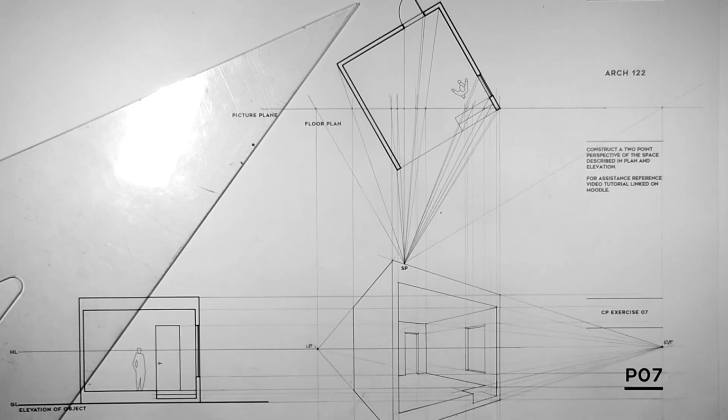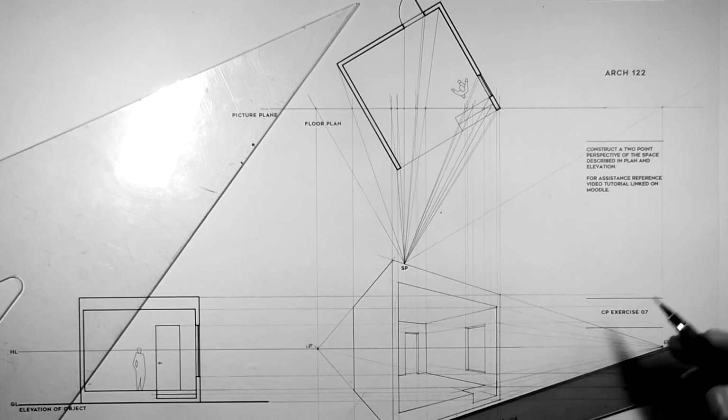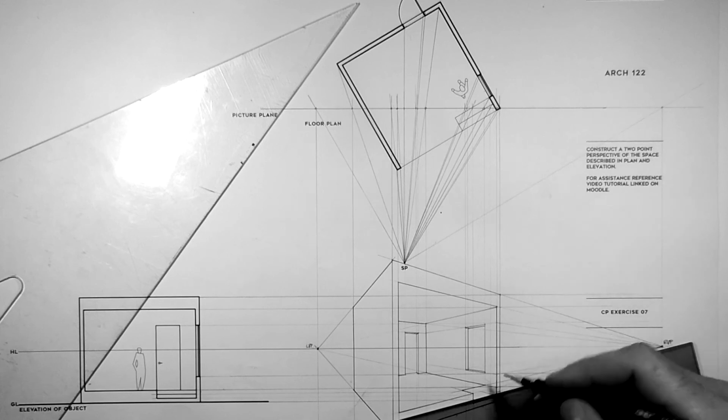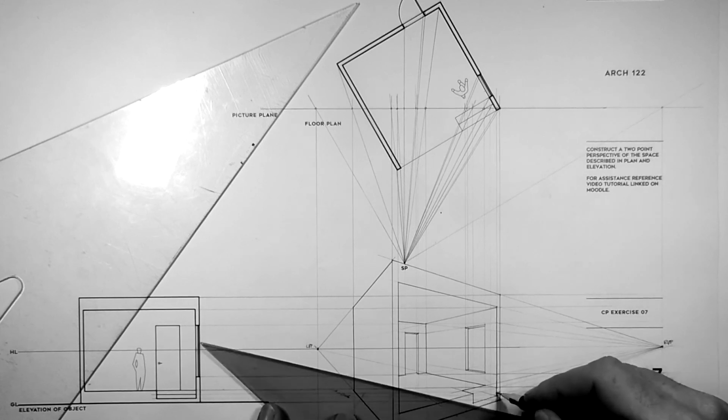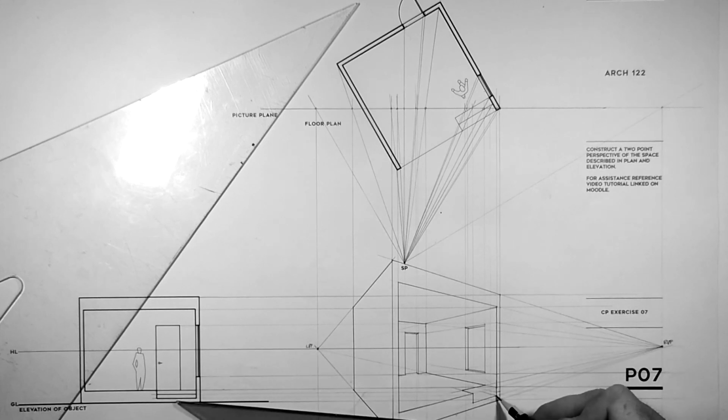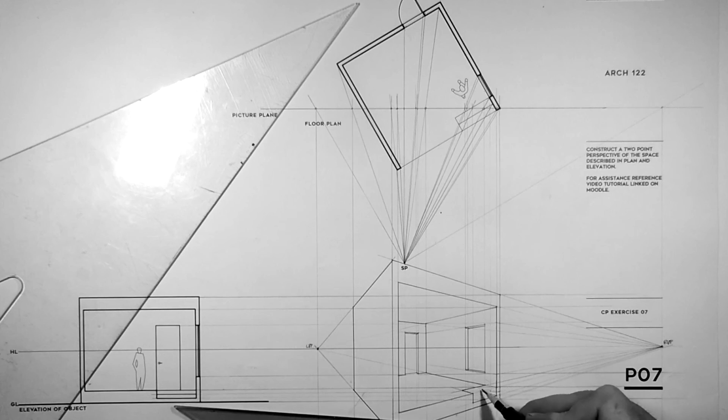Now we can darken that a bit. Well, not quite yet. We need to figure out where it stops. So to figure out where that line stops, we've got to come back and bring this height to here from the elevation. We've already projected it over to the true height line. And now from that true height line, we need to bring that height around this wall here. So we translate it there, and then we're going towards the left-hand vanishing point to go back along the wall. And we can translate that there. So now we know our step ends there, goes back that far, goes up that far, back that far, and up that far.